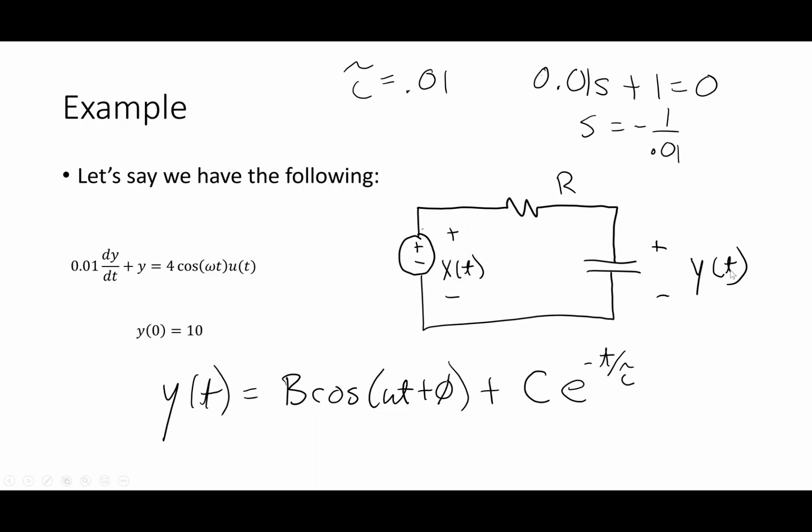All right. So last time we looked at a first order differential equation, how to approach this numerically. I took an example circuit. If you started looking at the project, the first two problems on there are first order problems, kind of similar to this one, where I've got an RC circuit like this, and I need to figure out how to approach this numerically. So I want to refresh where we were with that, and then jump into the approach we would take with second order.